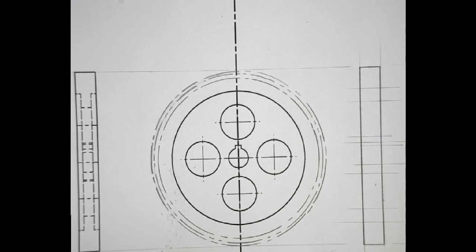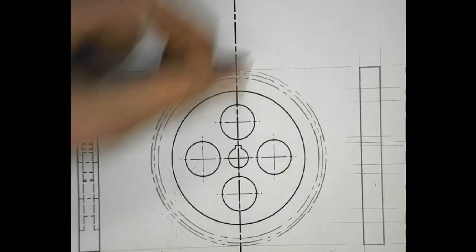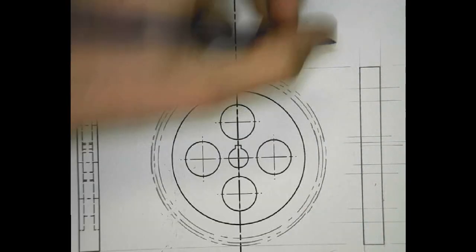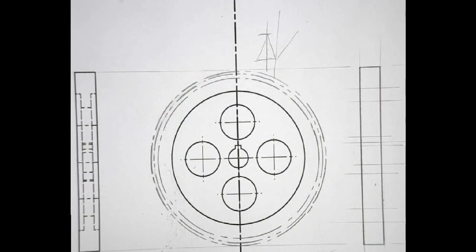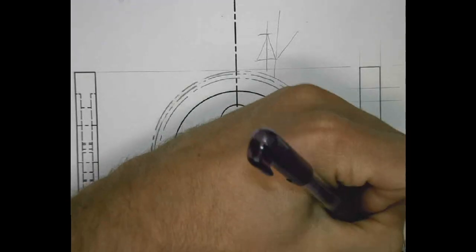We'll then also indicate details with regards to our gear teeth. So in the question it says that you must assume that the cutting plane cuts through the center of the teeth at the top and bottom. So we can assume that we won't see the root diameter of that tooth because we are cutting through a tooth like that. If we were cutting through over here, we would see a solid line here as well as a solid line there. But what we will indicate on here is a dotted line for the pitch circle diameter of our gear.